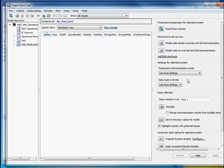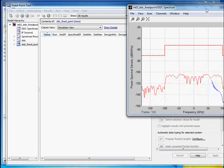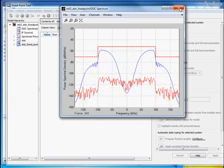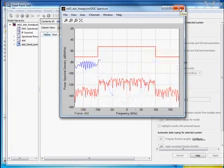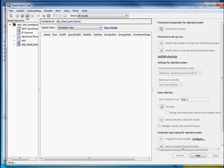And what we'll do here is, first of all, we need to instrument the design by logging the mins, maximums, and overflows. So we'll go ahead and rerun the simulation. And we're seeing the same response here, just that now we're capturing all that data. We'll let that run a few seconds. And then we'll go ahead and stop the simulation.